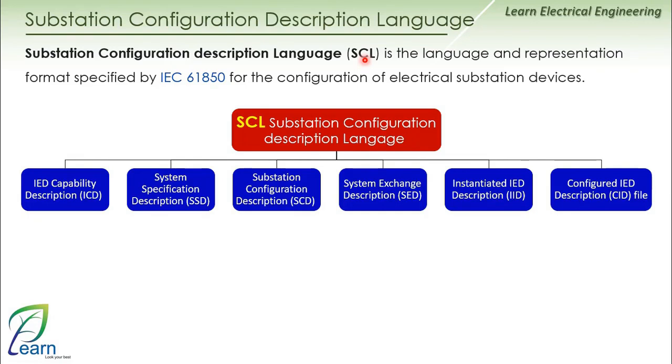And when we talk about the substation automation system, you have a set of relays in the field that transmit a set of statuses, alarms, indications, and measurements, and they receive commands from the SAS. What about relays communicating with each other? Yes, of course, relays communicate with each other through something called GOOSE messages.